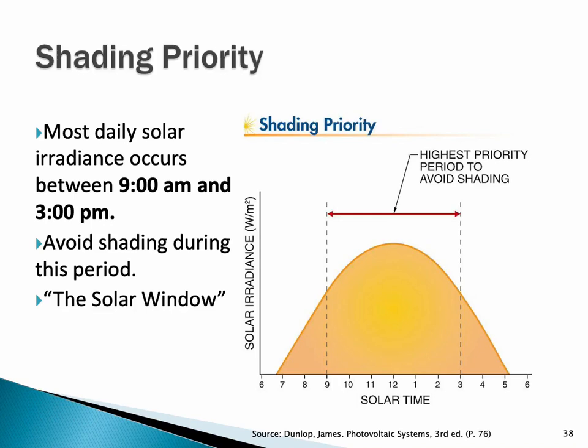So our sweet spot for production is this time period of 9 a.m. to 3 p.m. That's when we make 88% of our energy. If you look at the Solar Pathfinder chart, add up all the numbers between 9 in the morning to 3 in the afternoon, regardless of month, it always adds up to 88%. And then the shoulder times, before 9, after 3, we make energy too, but not of the same intensity. So shading is really critical.